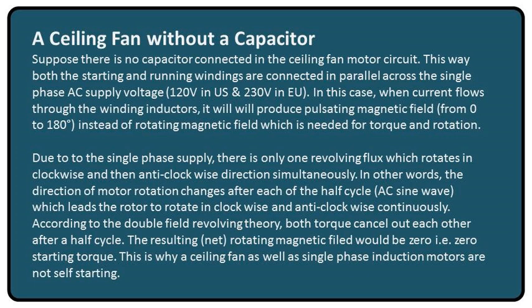According to the double field revolving theory, both torques cancel out each other after a half cycle. The resulting net rotating magnetic field would be 0 starting torque. This is why a ceiling fan, as well as single-phase induction motors, are not self-starting.